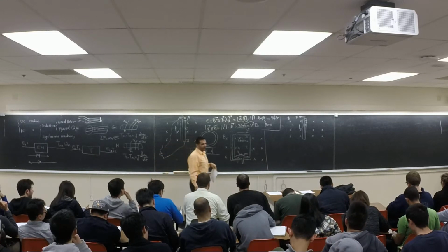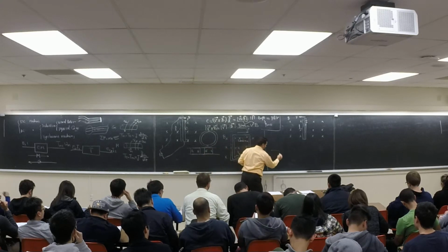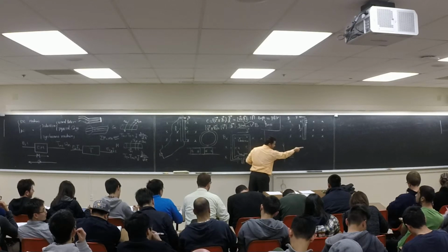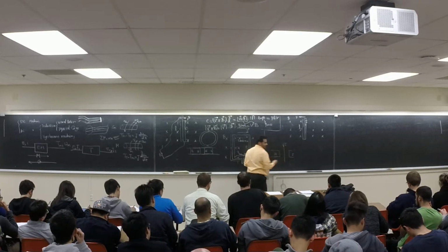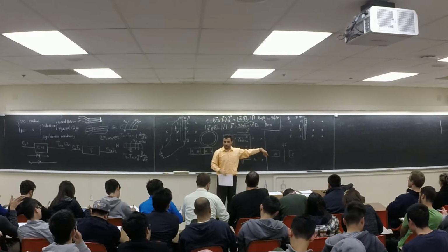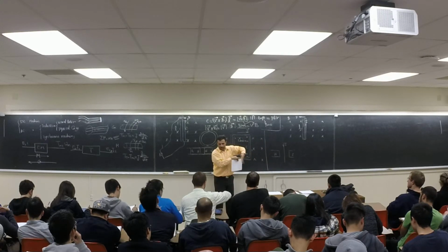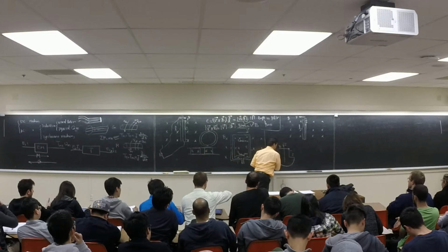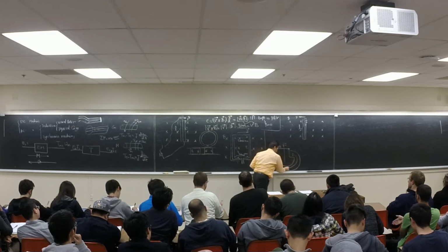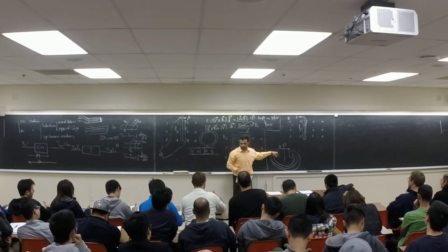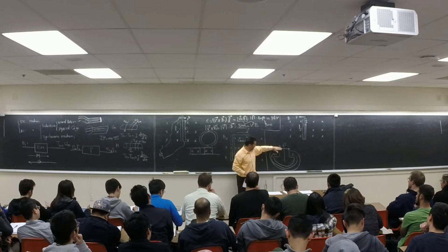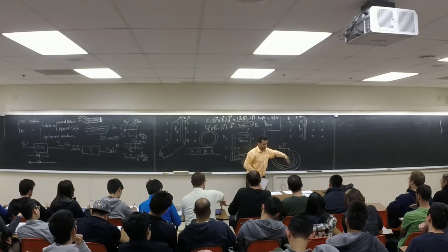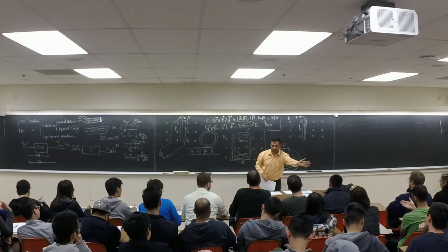The example I put on the board now, I can tell you what the direction was. Remember, it said N here, right? It said S here, right? And we had this wire here, and the polarity was up there, so the current was like this. To find the direction of the movement, B should go from N to S. Inside the magnet it is from S to N, outside the magnet it is from N to S. So B is going this way, I is this way, so the conductor is going to move this way, toward the outside of it.